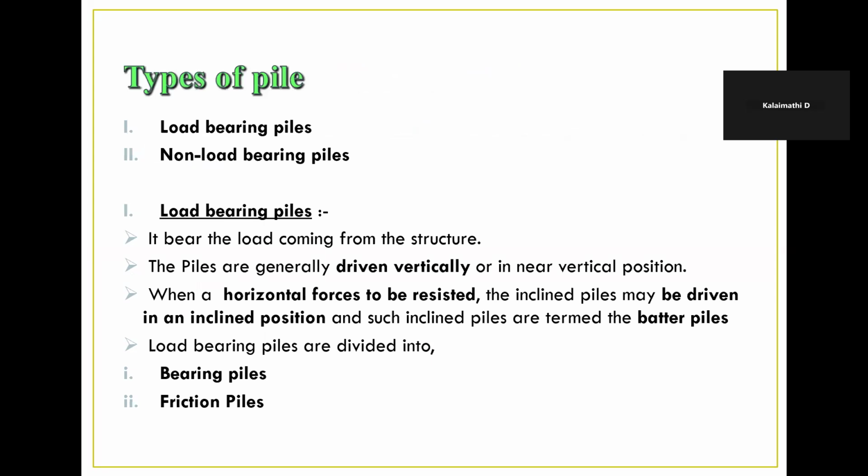And then the types of pile. For pile foundation, the piles are load bearing piles and non-load bearing piles. A load bearing pile bears the load coming from the structure. The piles are generally driven vertically, and where horizontal forces have to be resisted, inclined piles may be driven in an inclined position. Such inclined piles are termed batter piles.